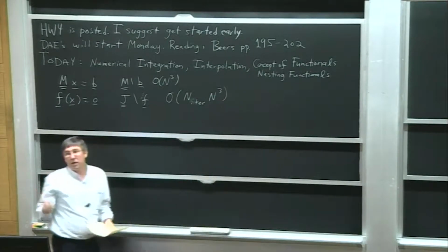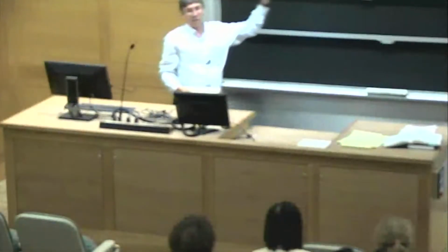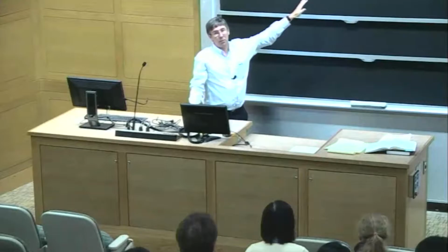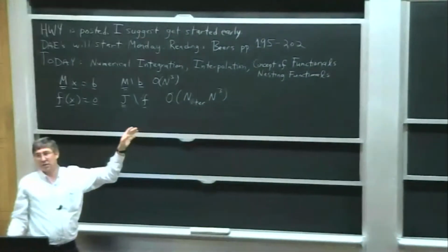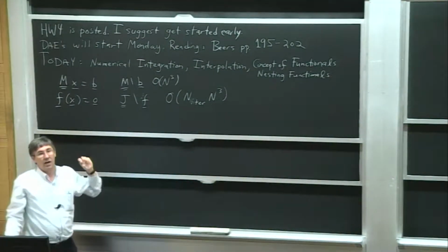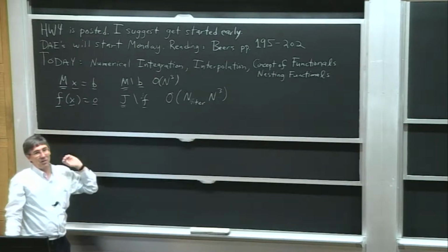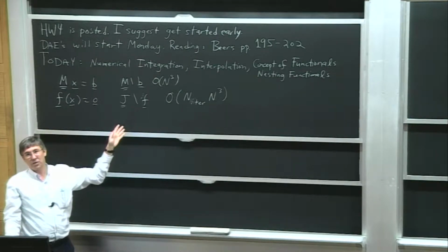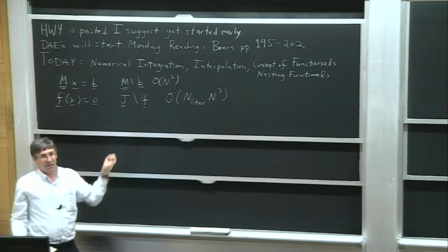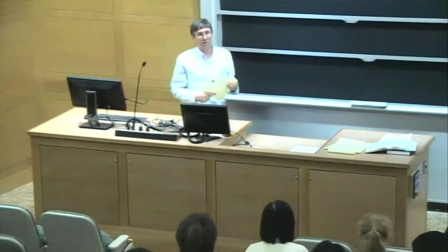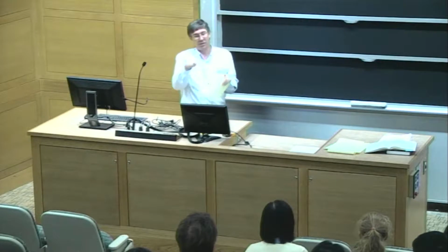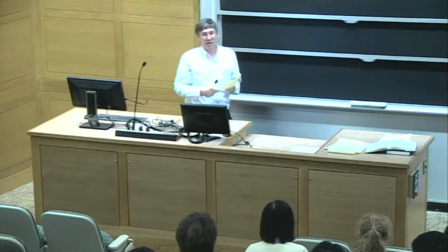Now, if you really can make Newton-Raphson work, and you have a really great initial guess, the number of iterations is really tiny because Newton-Raphson has such fantastically great convergence. However, we're usually not such good guessers, and so it might take a lot of iterations. And in fact, we use the dogleg method to solve this, as we discussed, where you mix up different methods and you have a trust region and all this baloney. And so it might actually be quite a lot of iterations to get there.